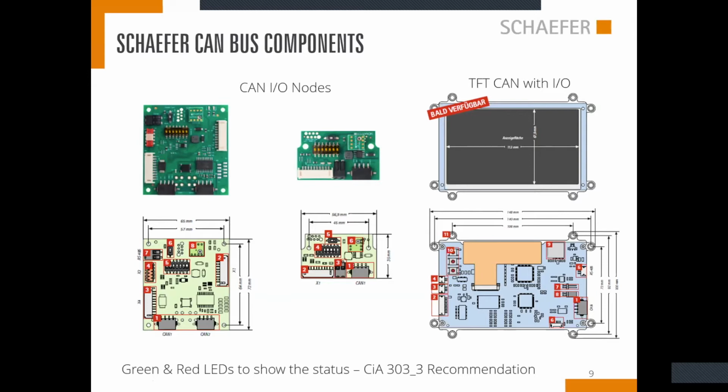And maybe if there is some issue where some of the IO modules stop working, then the customer could just buy a new CAN module from us, and even though he doesn't know what has been configured at this particular installation, he could take out the old EEPROM from the old CAN module and plug it into the new one, and he could have intercompatibility.